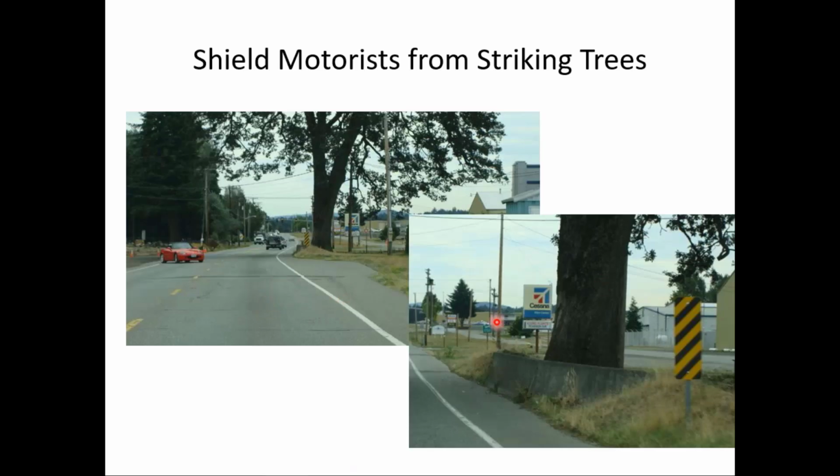So you notice there's a concrete traffic barrier here with earth mounds on either end to avoid striking the blunt end of those barriers. And there's also the object markers to identify the fixed object along the roadway. So I thought this was kind of an interesting approach.